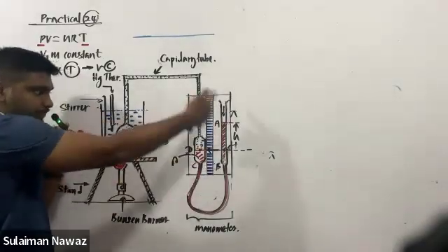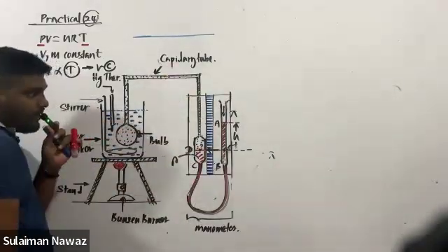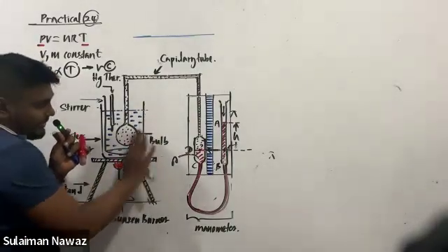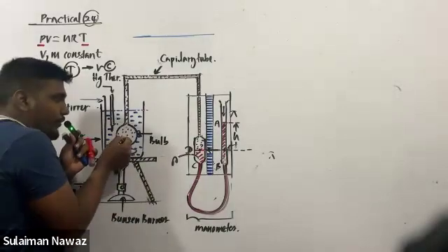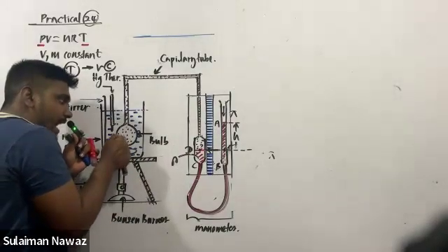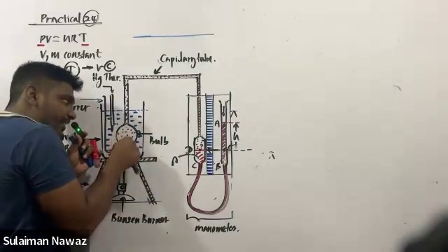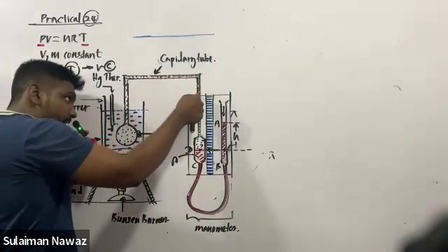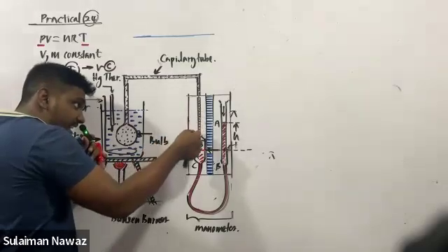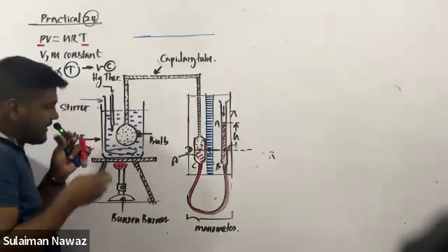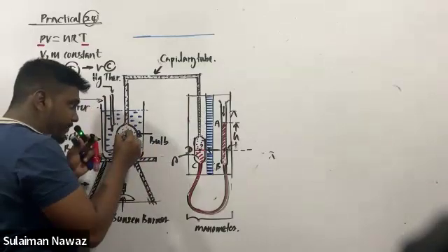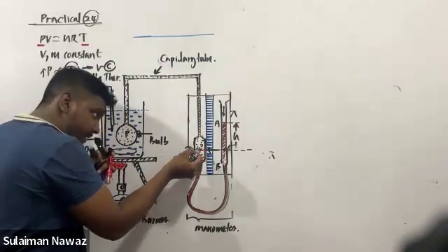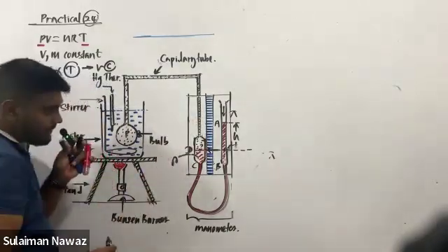Using this manometer. Right? Using this manometer, what will happen? Let's say at a certain temperature, you want to measure the pressure of the gas. We know that at a certain temperature, pressure at any point in the gas is the same. I say the pressure of the gas is capital P, for example. What is the pressure at point D? Pressure at point D is also capital P.